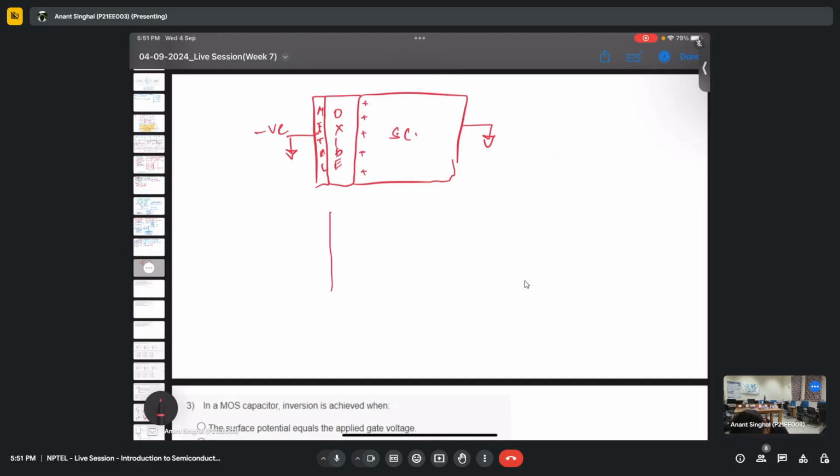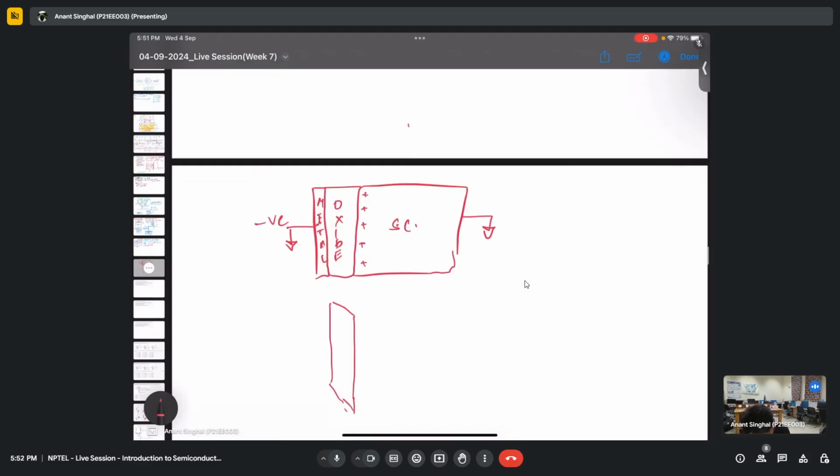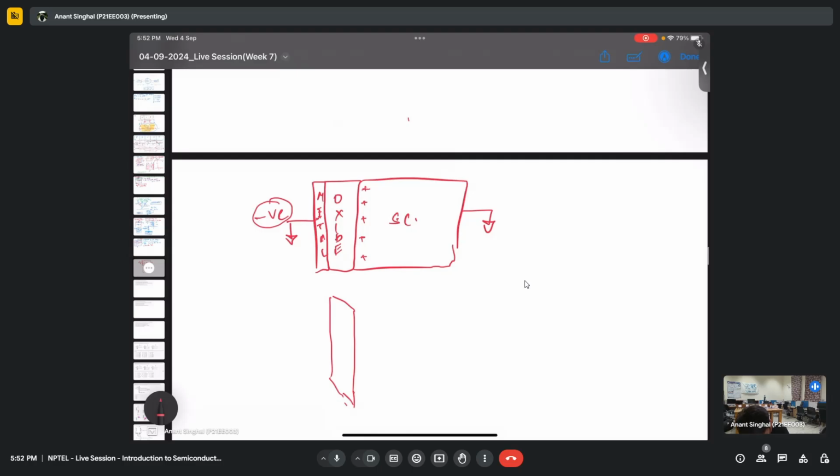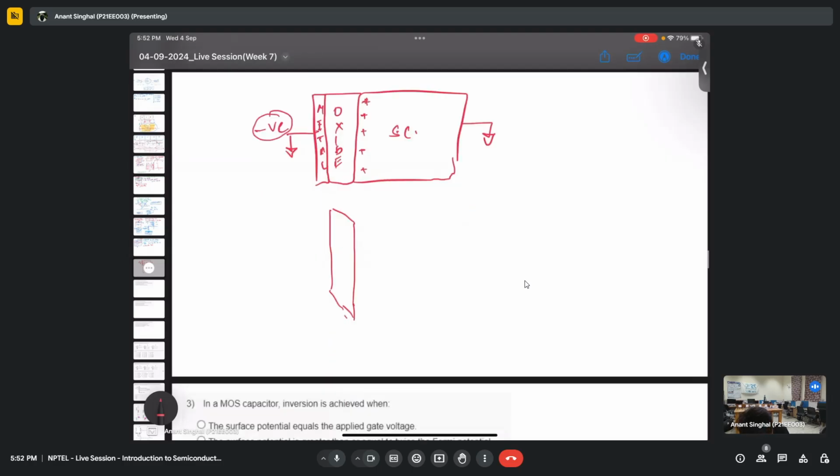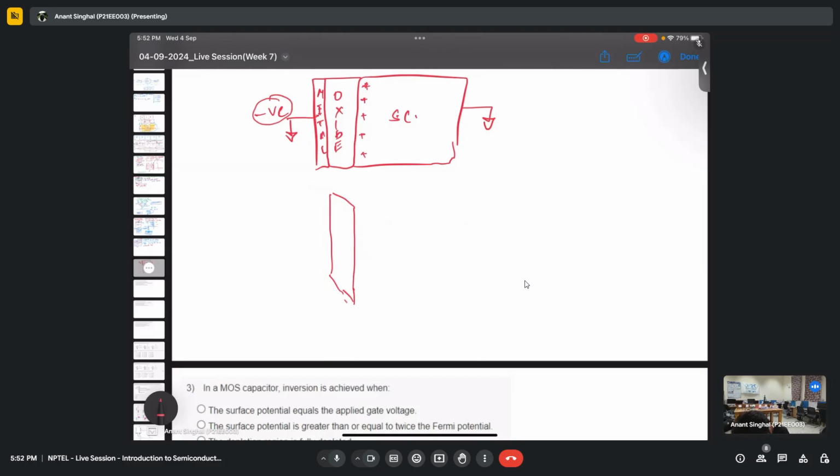I can just leave out the oxide part. The negative bias attracts these holes, and so we have band bending upwards, because we have a higher Fermi level here and a lower Fermi level here, so it will go down. That means it will bend upwards. So maybe I can make this EFM very high. That is not a problem.